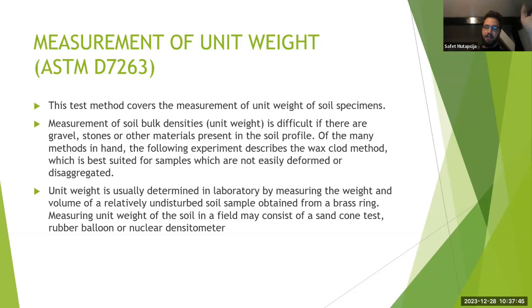So it's basically it. But for coarse grain sand, for the sands or the gravel, I would say that's fine to use. But for the clay, I wouldn't, just because of the calculations and everything that you need water content for. You also need it for the void ratio calculation for the settlements. So it's a pretty important standard, even if it sounds really simple and maybe stupid, and you're going to hate it if you do it like 1,000 times. But it is one really important test.